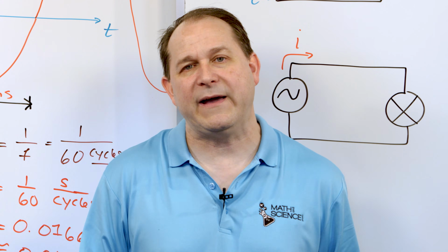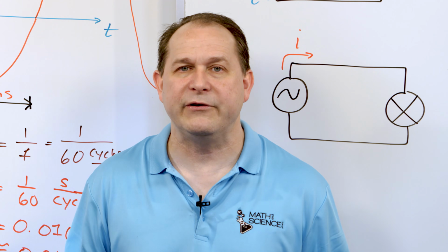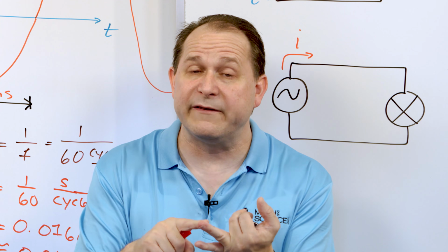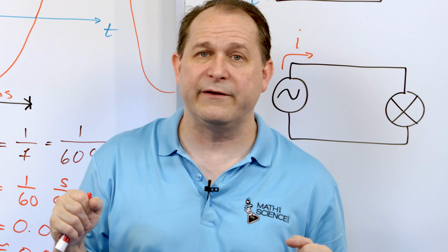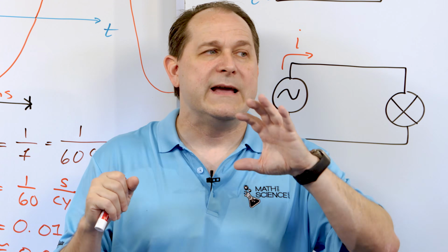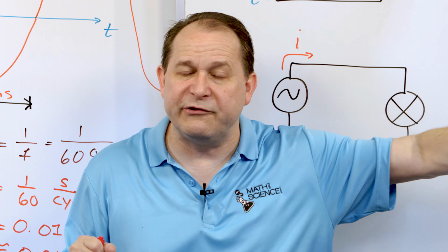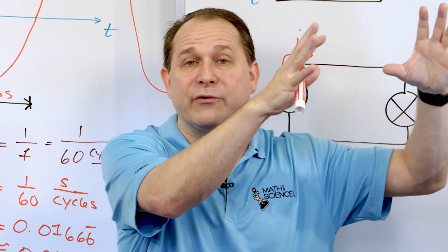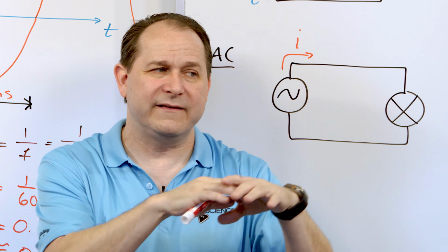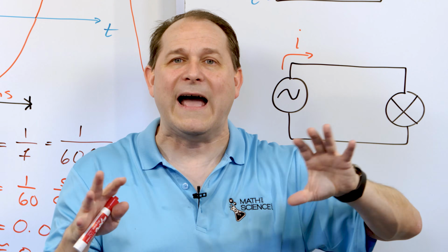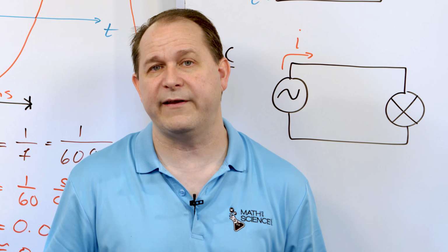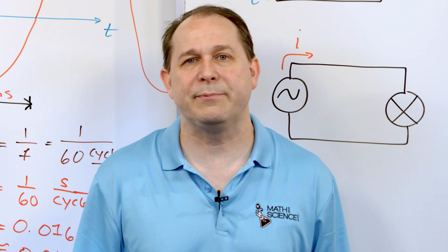So the reason we have AC electricity so predominant in everyday life is because it's easier to generate. And then when we want to transmit it, we can step up the voltage with a transformer, only we can do that with AC, into very high voltage for transmission across the wires without very much losses. And then when we get to the houses, we have transformers that can step it down to the substation, not directly to the house, to the substation and to the neighborhood. They're stepped down to these low voltages that we can use. So it's easier to manipulate the voltage.